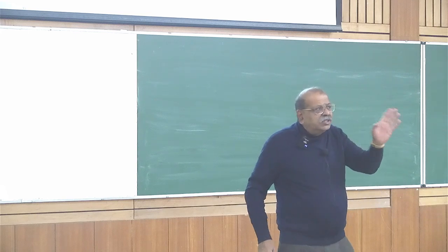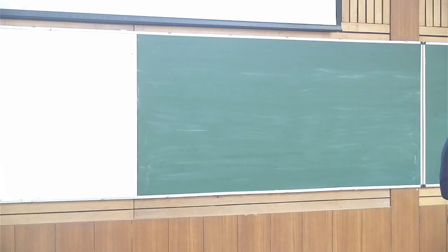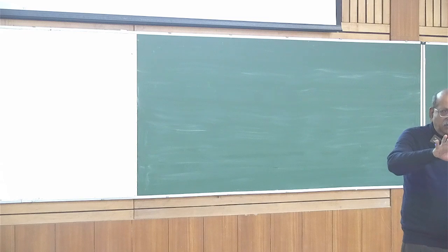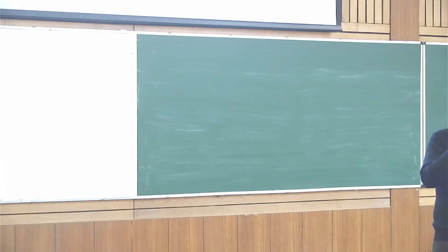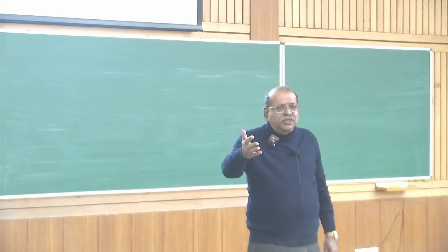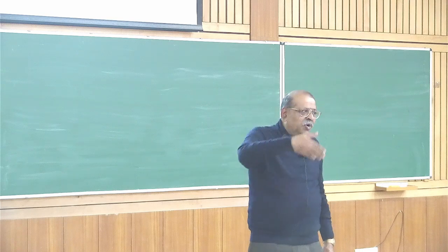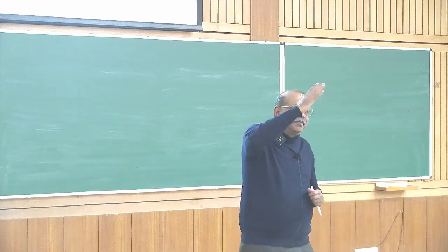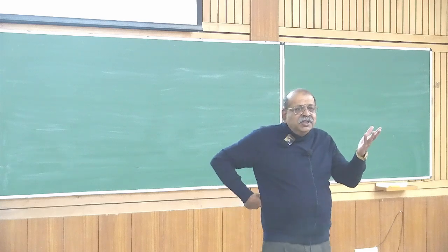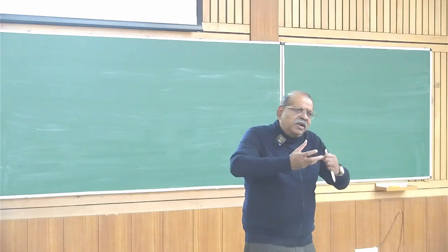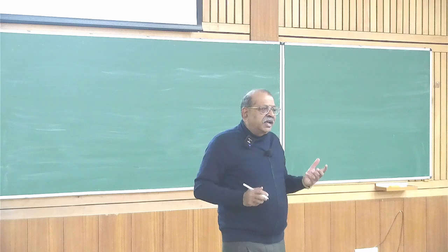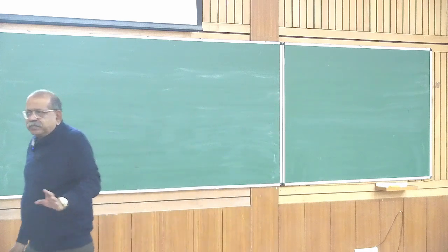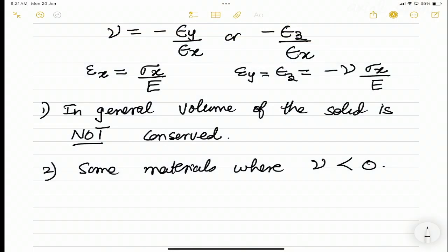But I think one take home which I want you to have is that for each loading, whenever we draw the simplest loading first, at least in your mind, you should think of the Mohr circle for that loading, so that you know what is happening in the other planes and where the shear is also maximum, or where we have a loading where there is only shear, then in which directions do we have a tensile load. Okay, thank you. So now we will meet on next Monday.